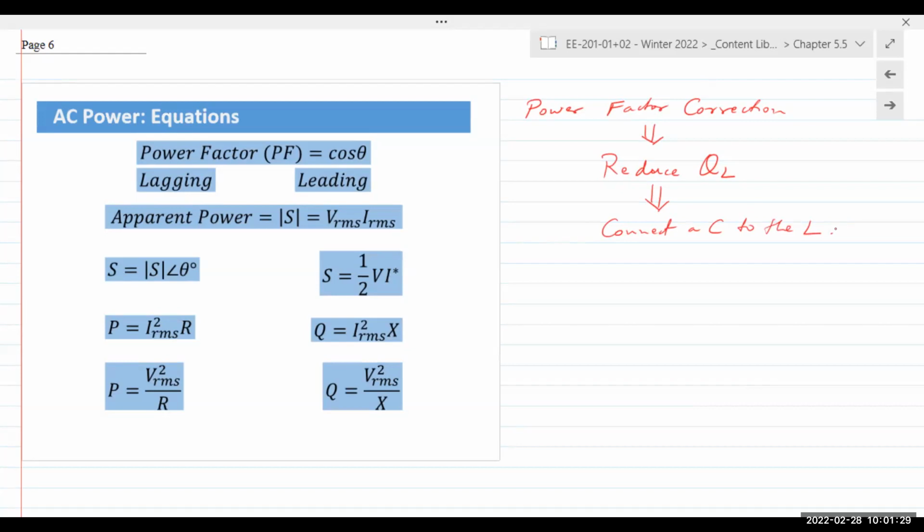So once the switch is flipped on, the inductive load receives the power in one half cycle, and in the next half cycle, when the inductor reaches steady state and is going to send all of that reactive power back to the utility company, the capacitor sort of intercepts and receives all of the energy.